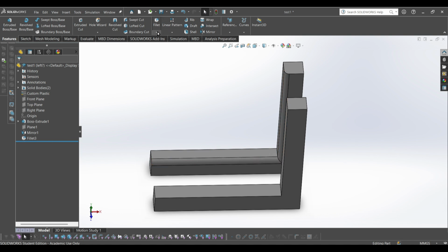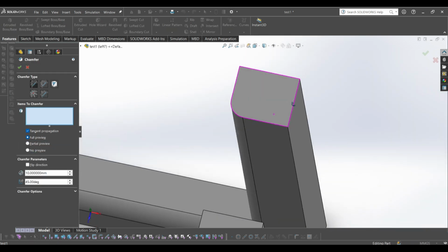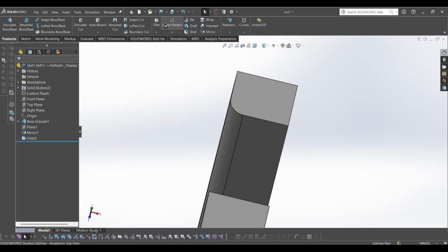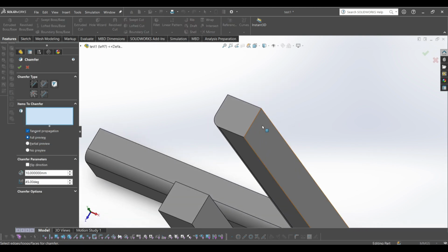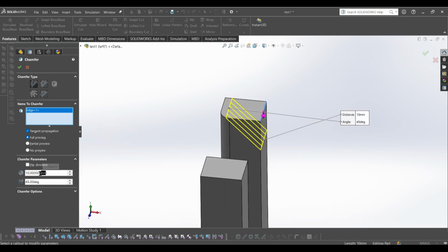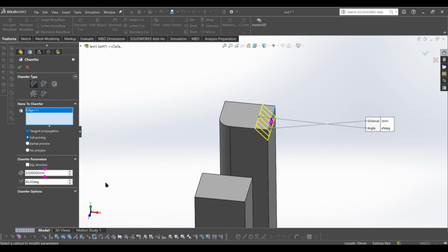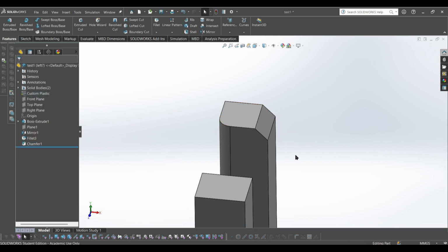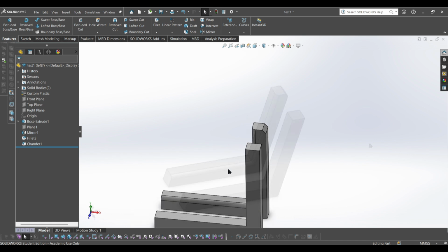And chamfer is the same thing, but instead of a curve, it adds sort of another face. So if I click on fillet and I click the drop down menu, I'll get an option for chamfer. And I can select an edge over here, and as you can see, it adds another face to the edge, and similar to the fillet option, I can change the amount that it gets cut off. And there's also multiple other settings in the Fillet and Chamfer tools, so feel free to play around with those if you wanted to explore.